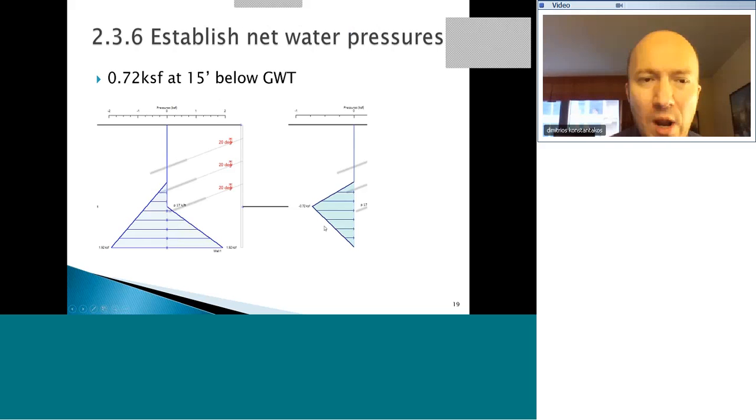So once we have the water pressures, we'll see that right at the excavation level, we have the maximum net water pressure, and then below, it drops to 0 at the bottom of the wall. Now, if somebody was to assume hydrostatic water pressures, there will be a slightly different value here, but the diagram will be constant. There will be a question, though: if you have soil under you, you will be getting flow.